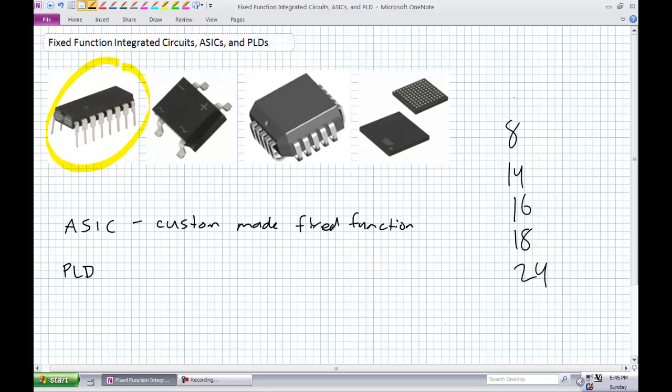So you're going to go to an ASIC vendor and say, hey guys, I want you to make me this chip. You're going to go through an expensive test and verify, and they're going to mass produce an expensive chip for you. That's going to be awesome because it's going to be optimized for your particular use, and it's going to do that one function exceedingly well. But next year, when you want to upgrade the factory, or change how it works, you're out of luck because you've sunk a lot of money into this application-specific integrated circuit.